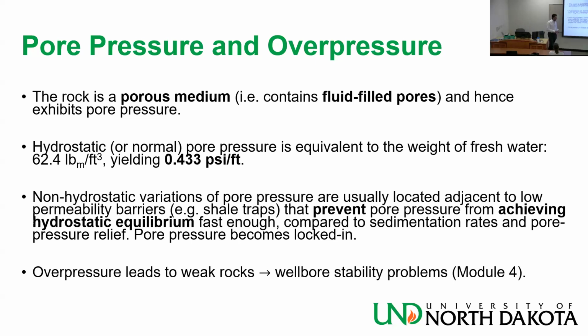It provides resistance in all directions, basically. And it acts the other way than the in situ stresses are acting. So if SV is acting that way, pore pressure acts the other way. It counteracts it, makes it smaller, so the rock is weaker.